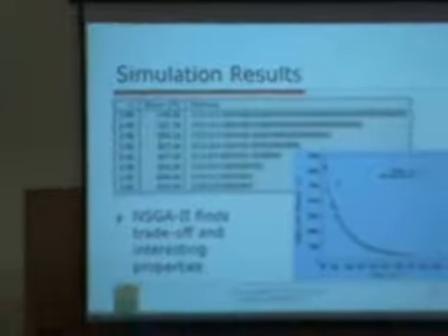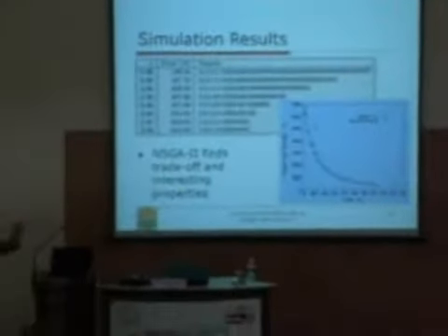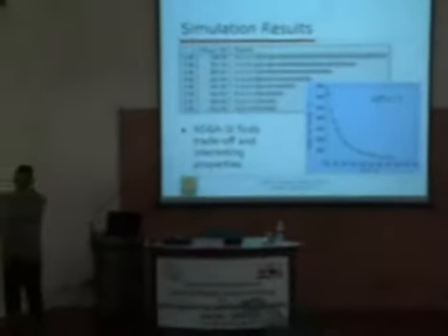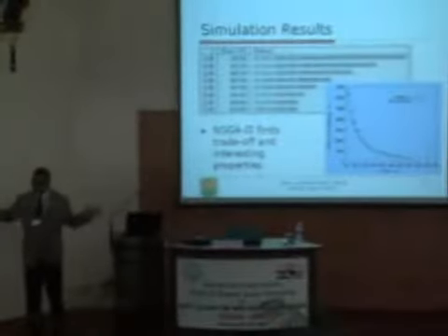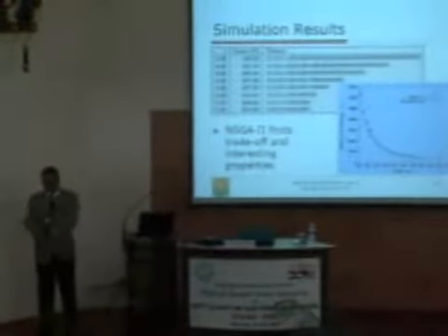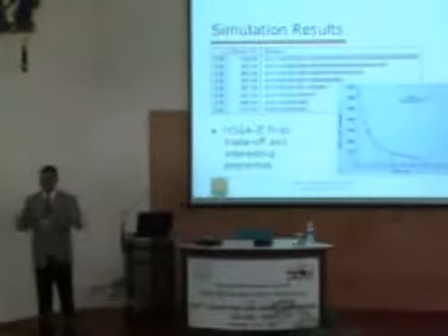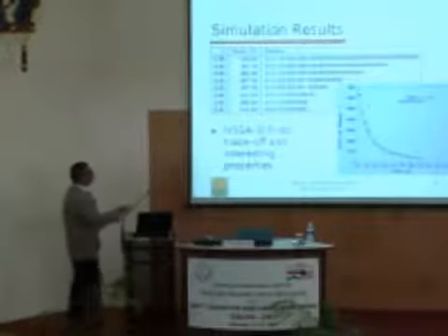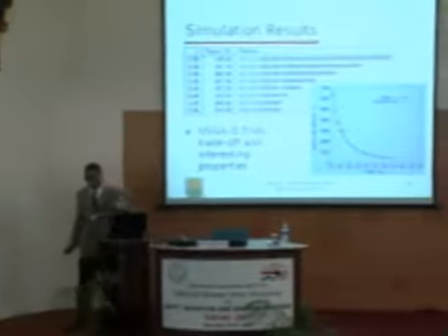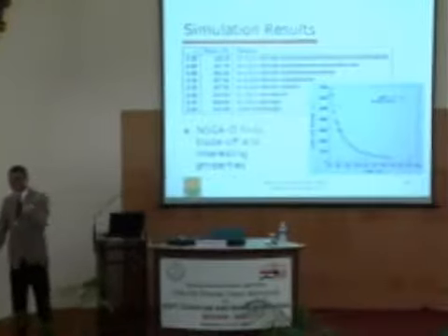Because if you push it too far at the end, it's going to go and bang onto that stop, and that's going to introduce a lot of sway. And then you have to wait till the sway reduces before you can drop it. So you'll be wasting a lot of time. So the algorithm comes out with this as a good strategy, that you only have to push it in the beginning and not at the end.